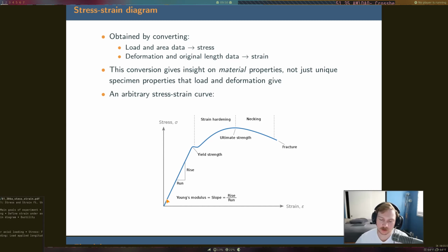So what you want to do is choose a value, let's say somewhere around here for your low end, and then for your high end, somewhere around here. I know it's kind of arbitrary in a sense, but you want to make sure that you're within that elastic range and that you have a decent spread.